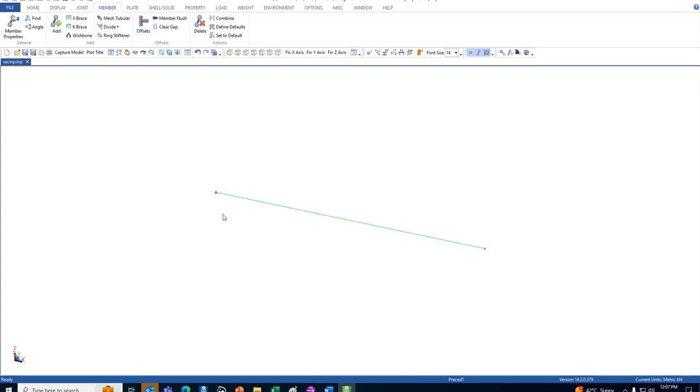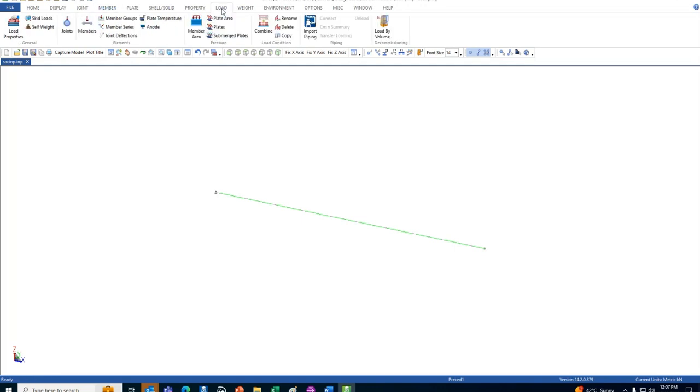So I created only the geometry and all these things, and load I have not yet defined. So I'll put load in each case. I'll put all the 6 degrees of freedom loads at one point. If I put load here, it will automatically add additional moments and all, right? Because fixity I have given here, whatever force I am applying, it will give additional bending and all, right? And it will give the shear stress also.